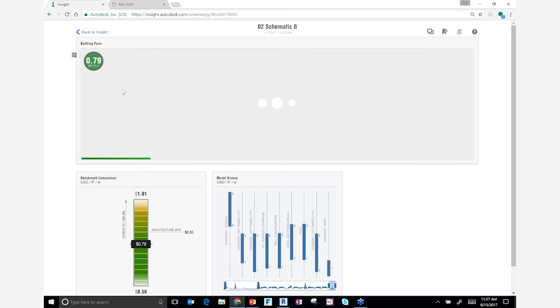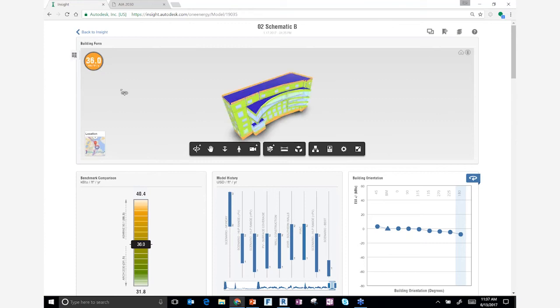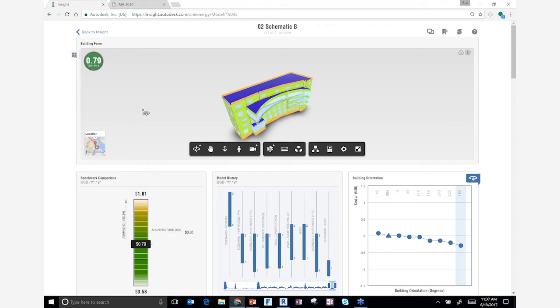There's different preferences for both. Naturally, the 2030 goals are based in EUI, but a lot of owners and clients don't actually understand EUI. Is 36 good? Is a saving of 6 good? But everyone understands running cost. So we like to leave the default as running cost because as you're driving one, you're driving the other as well.